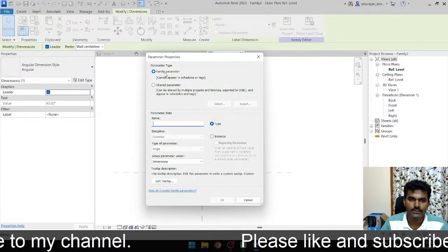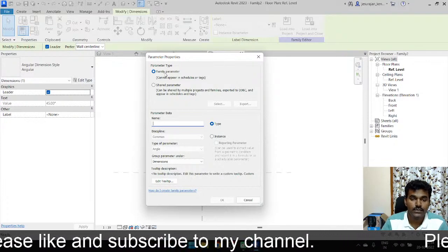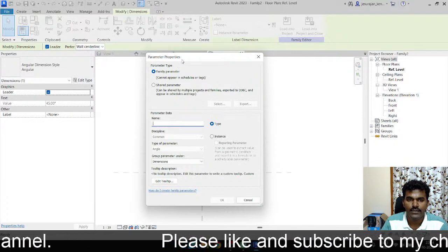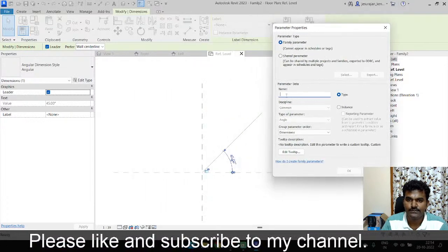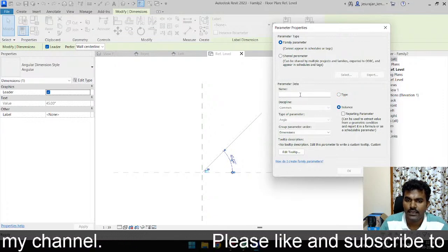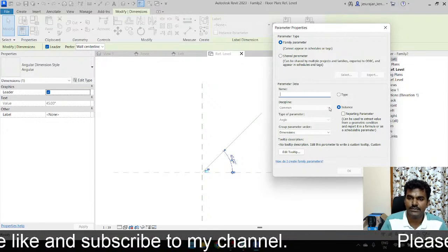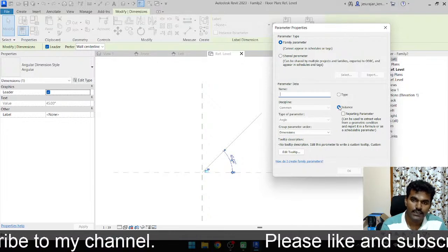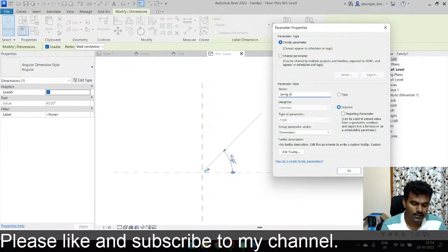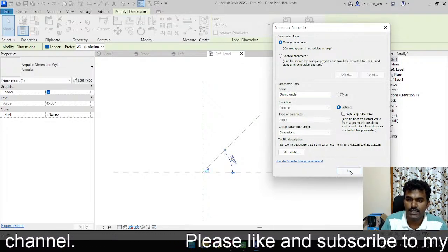Anyway, we can edit our family anytime and change our parameter. For now, to make it easy, I'm making it a family parameter. Select and keep that as instance, because we are going to take this family as a nested family. Keep this as instance and give a name: swing angle.